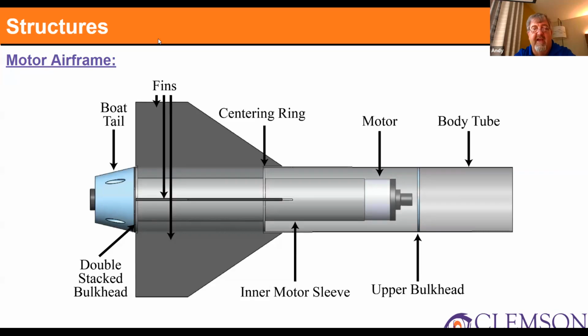Again, for future designs, instead of doing a separate bolt, just have a single bolt with a bunch of washers and nuts and such, and put an eye bolt towards the end of it, so that you could just attach your shock cords directly to that. That would make it very, very well anchored.